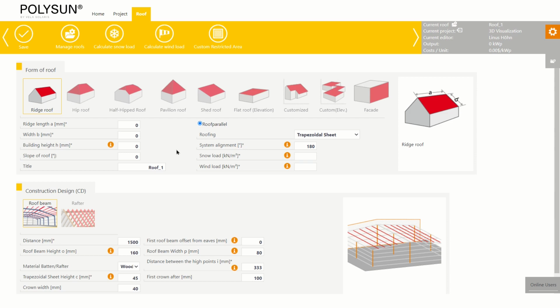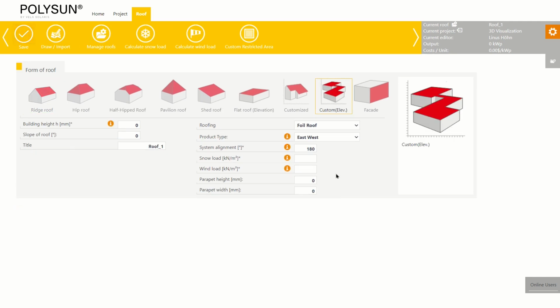In this video, I will show you how to create 3D visualizations of your projects. I have already created a project for this video. We're going to use a flat roof, so we choose the roof type custom elevated. I start by filling in the details and enter a building height of 10 meters.